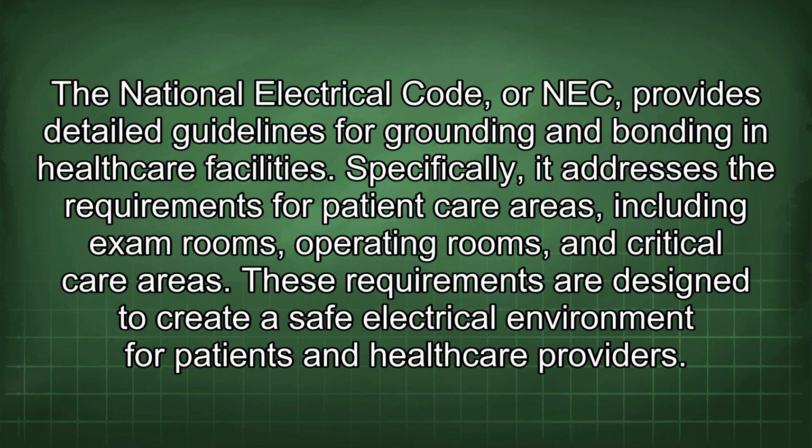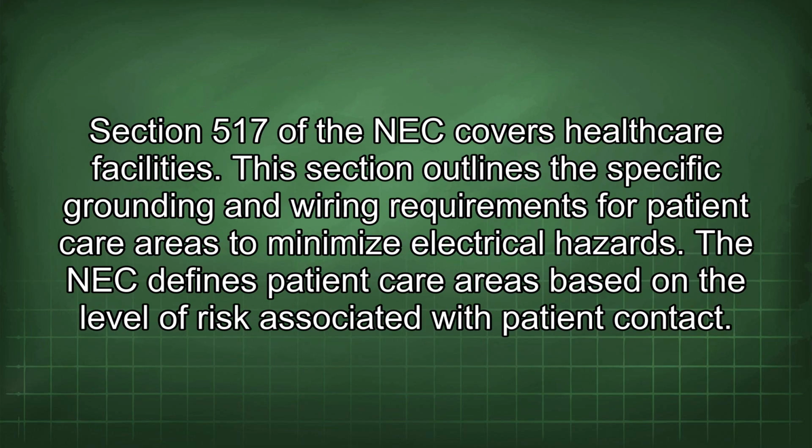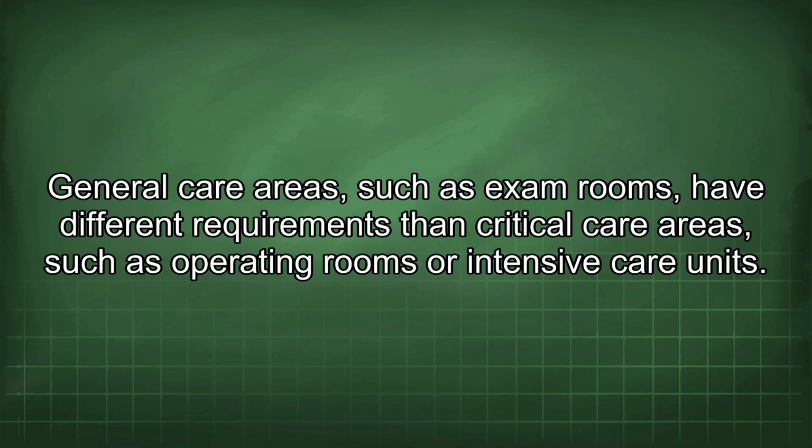Specifically, it addresses the requirements for patient care areas, including exam rooms, operating rooms, and critical care areas. These requirements are designed to create a safe electrical environment for patients and healthcare providers. Section 517 of the NEC covers healthcare facilities. This section outlines the specific grounding and wiring requirements for patient care areas to minimize electrical hazard. The NEC defines patient care areas based on the level of risk associated with patient contact. General care areas, such as exam rooms, have different requirements than critical care areas, such as operating rooms or intensive